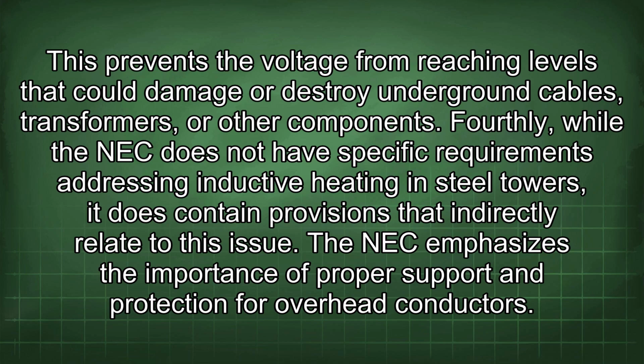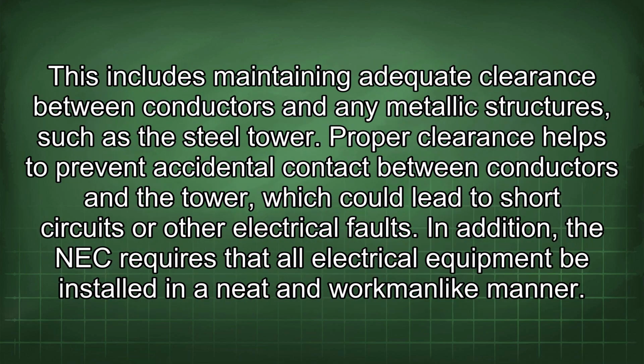Fourthly, while the NEC does not have specific requirements addressing inductive heating in steel towers, it does contain provisions that indirectly relate to this issue. The NEC emphasizes the importance of proper support and protection for overhead conductors. This includes maintaining adequate clearance between conductors and any metallic structures, such as the steel tower.